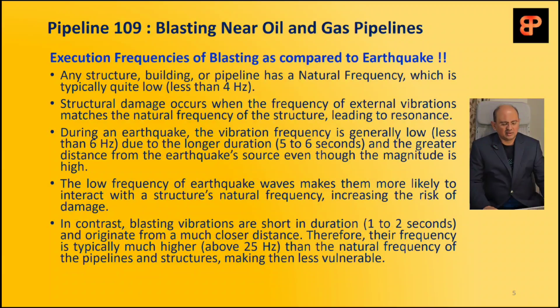In contrast, blasting vibrations, the vibrations induced during blasting, are short in duration, hardly 1 or 2 seconds, because it is normally a controlled blasting, and originate from a much closer distance. Therefore, their frequency is typically much higher, above 25 hertz, than the natural frequency of the pipelines and structure, making them less vulnerable.